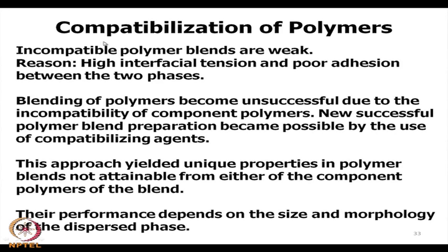Now, let us look into the compatibilization of polymers, component polymers to make a polymer blend. Now, incompatible polymer blends are weak, we know. The reason behind this is that there can be high interfacial tension between the component polymers, and at the interface poor adhesion is found between the two phases.